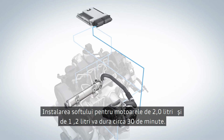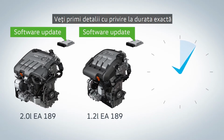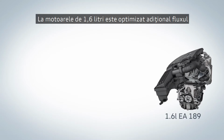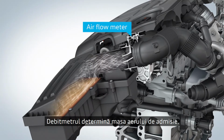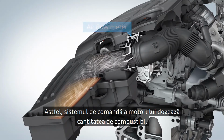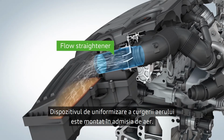The installation of the updated software for the 2.0 and 1.2-liter engines will take about 30 minutes. More specific details on timing will be confirmed to you when booking the vehicle in. For the 1.6-liter engines, the flow towards the airflow meter is additionally improved. The airflow meter determines the mass of the intake air. With this, the engine control doses the fuel quantity and regulates the exhaust gas recirculation rate. The flow straightener is set into the air intake.